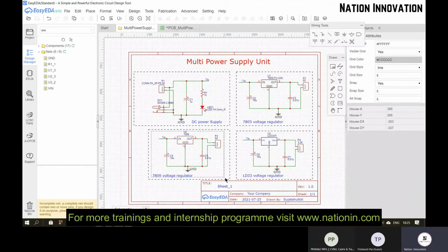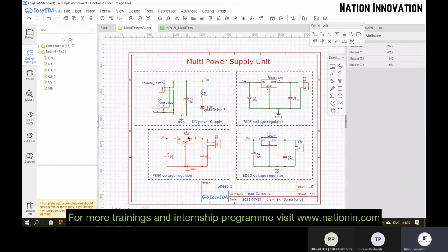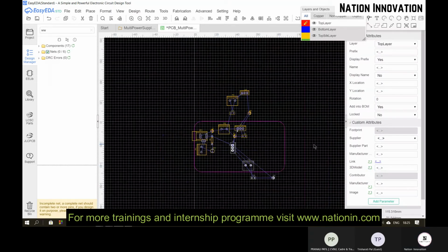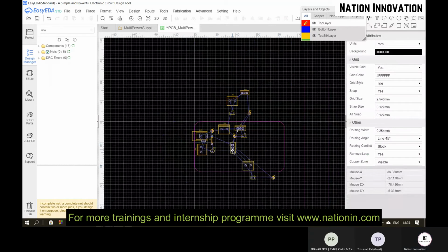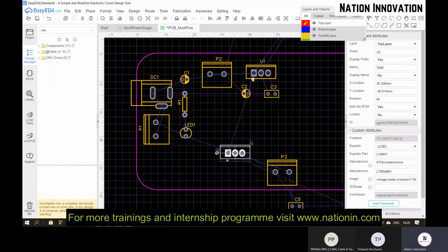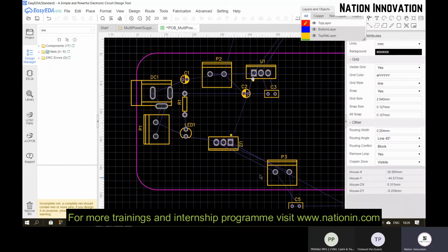So I have connected two capacitors, one IC and one pin connector. And again, I have a 7809 voltage regulator. For that, again, I will drag the components. Firstly, let me place the 7809 IC. So it has to be again facing to the outer border line.